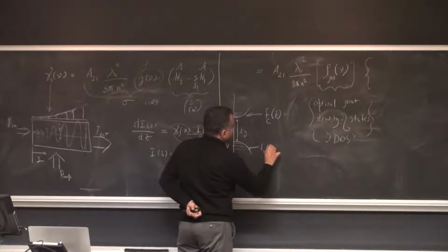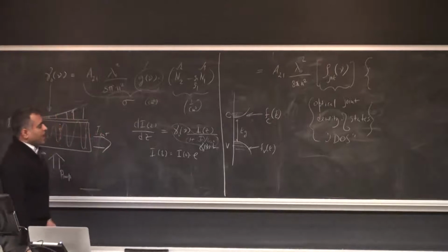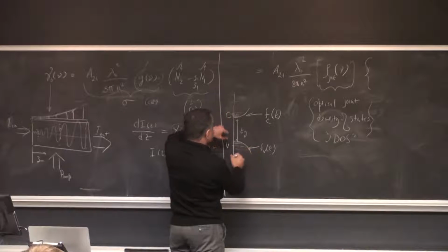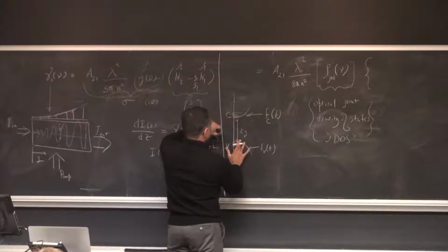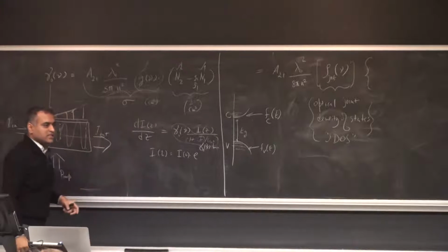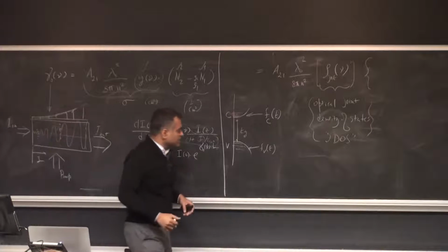And each one of them will have a separate Fermi function. Ideally, in every system, once you're in equilibrium, all the electron populations, whether you're in this manifold or that manifold, have the same Fermi level. But that's useless to me as a device, because in equilibrium nothing is going to emit light for me. So I'm going to have to force it to emit light.